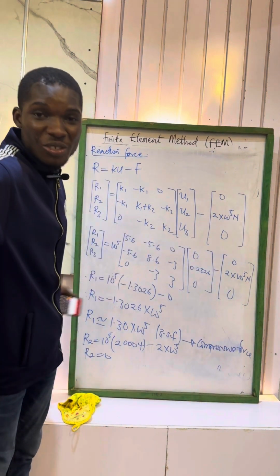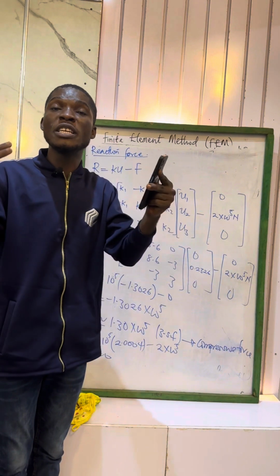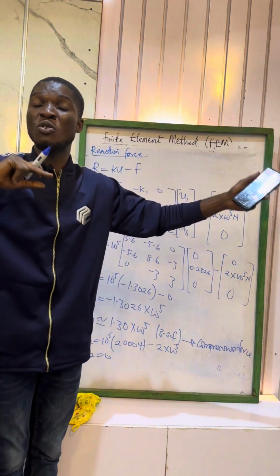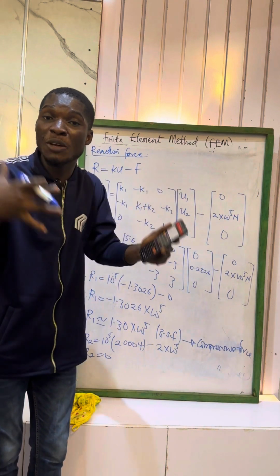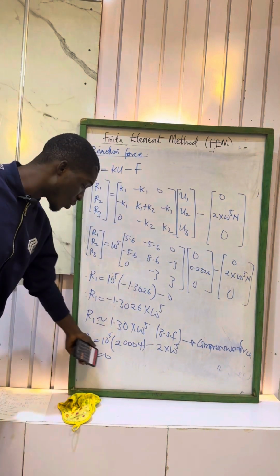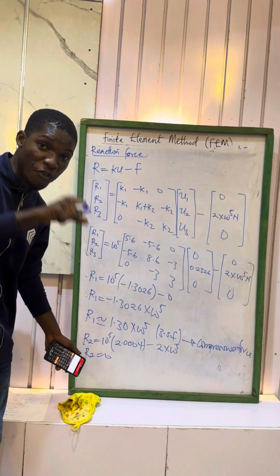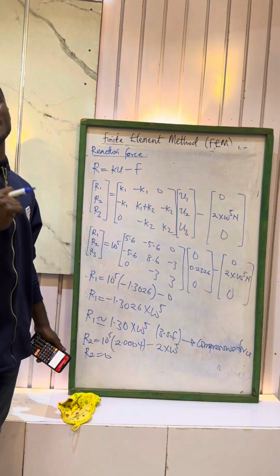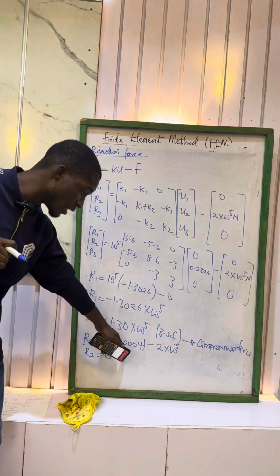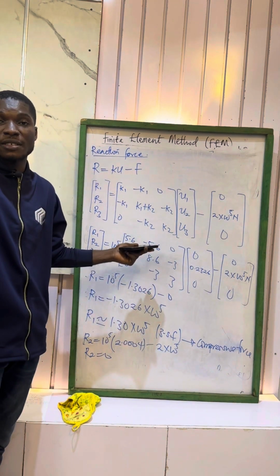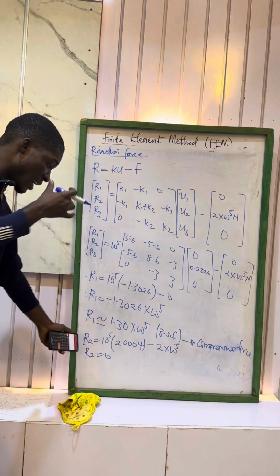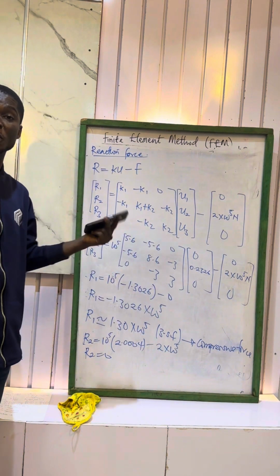Because at that point, there's a force of reaction. You're already having action there. And we say, when you do the summation of forces at a node, the action and reaction are equal but opposite. So when you sum them together, they become 0. So if you don't get 0 at the point of action of your force, it simply means you are having an issue with a particular calculation. Because this 0.004 is not significant, I'll just approximate it to give you 0. So the reactive force here is 0. You don't need to put Newton.